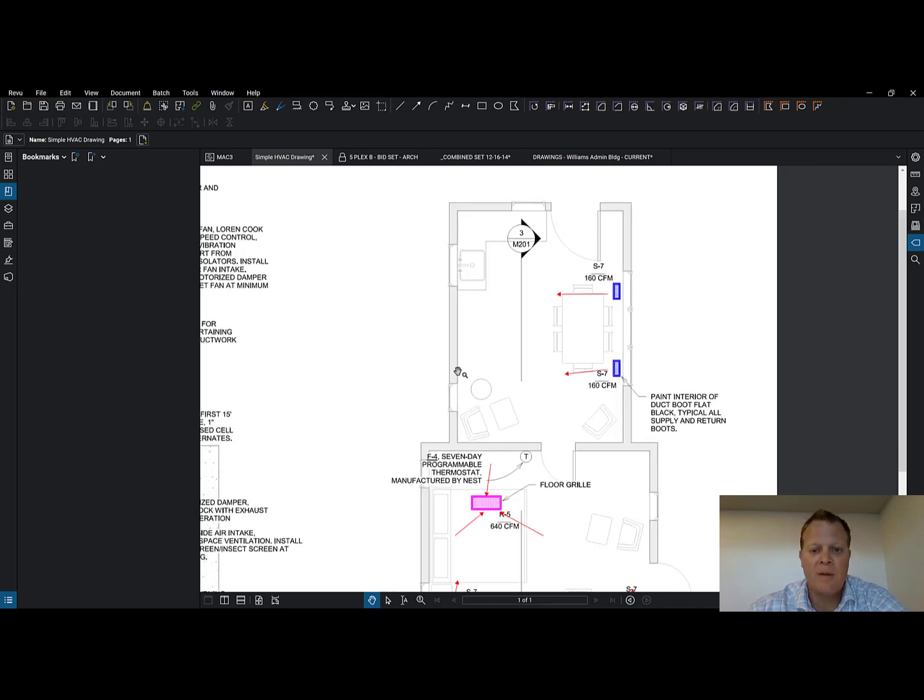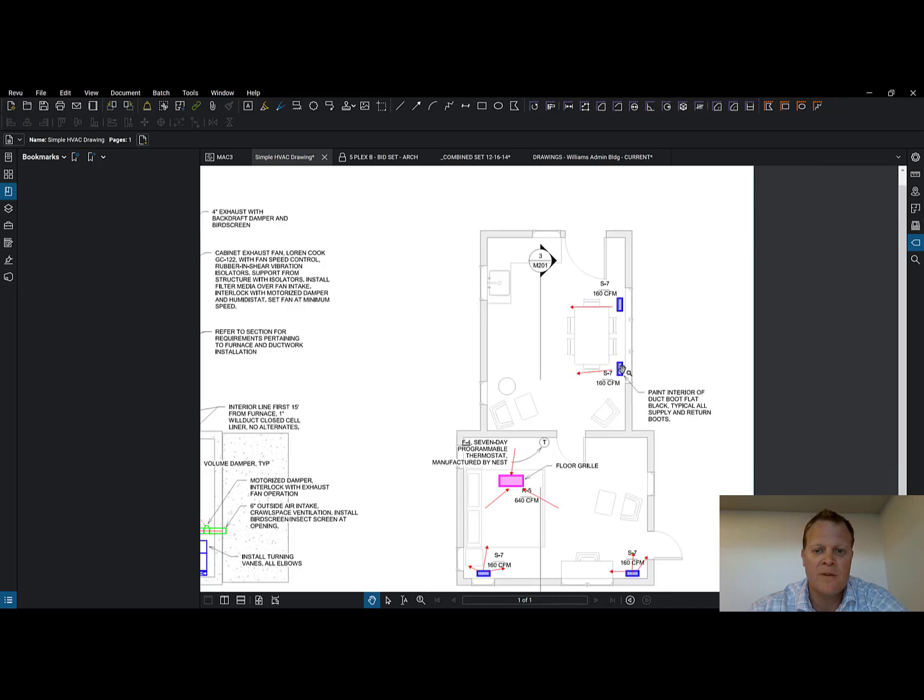So what if the framing down below we have 16 inch center TJIs or something like that, but that means you're down to like 14 something. So what if there's a TJI sitting right in the middle of this? Well, then that's not good coordination, because we need to head that off, or we need to do something else to be able to get the TJI to give space for this. So there's some framing coordination that possibly could happen right here. Why do they want the floor grill underneath the bed? Well, to hide it so that no one sees it.